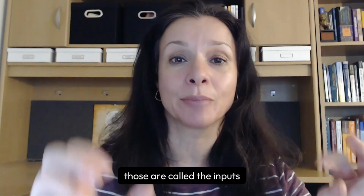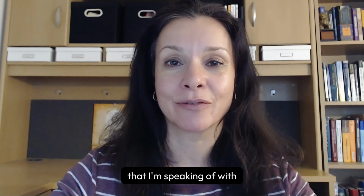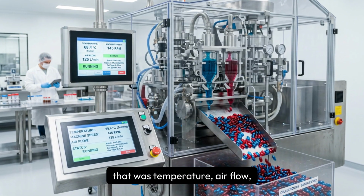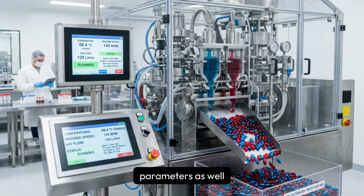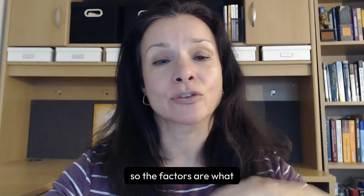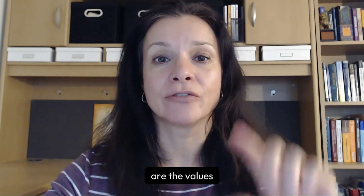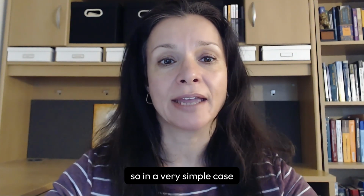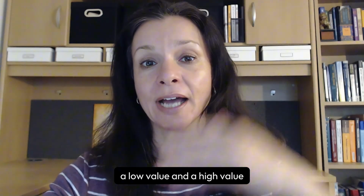Those are called the inputs. In this particular example that I'm speaking of in pharmaceuticals with the encapsulation machine, that was temperature, airflow, machine speed, gel type, and there were many other parameters as well. So the factors are what you're manipulating. And the levels of those factors are the values that each factor takes. In a very simple case, a two-level design, each factor has a low value and a high value.